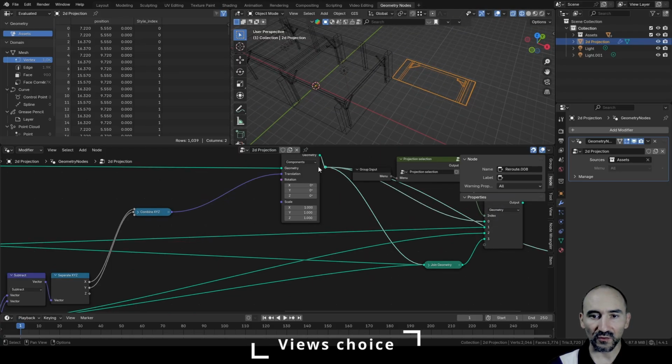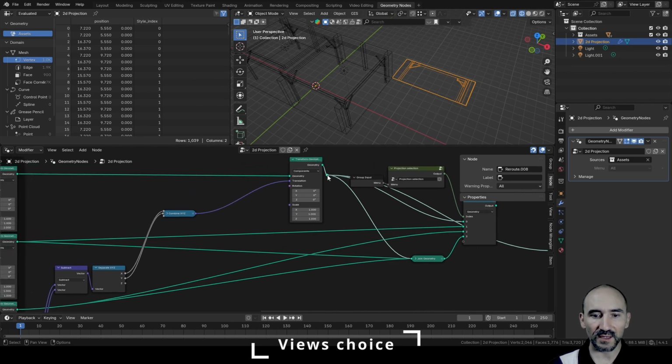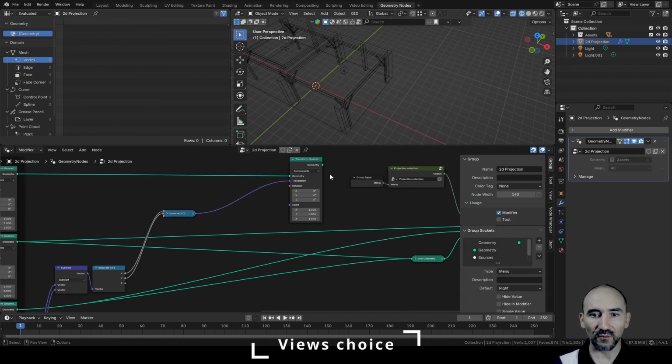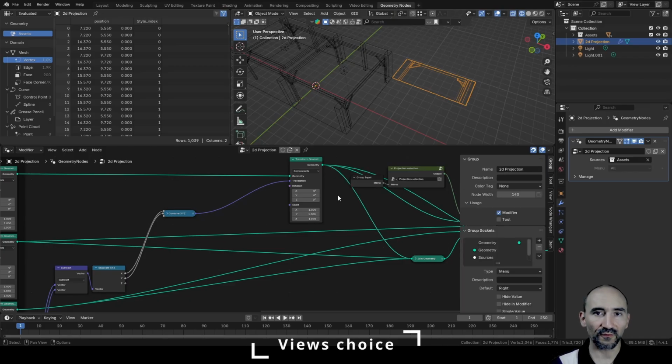I can drop this reroute with the Ctrl X and not X, because if you press X you delete not only the reroute but also all the connections in the input and the output of this node. So press Ctrl Z to undo and press Ctrl X to dissolve the node.